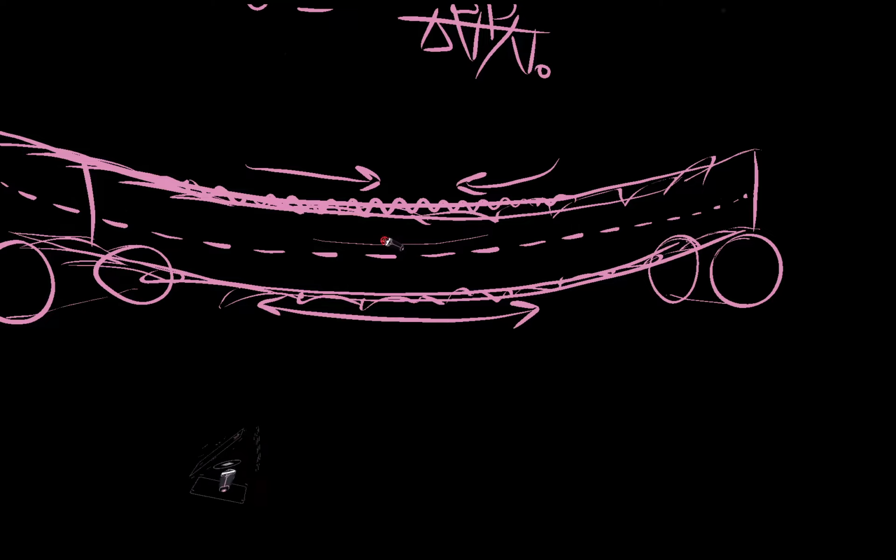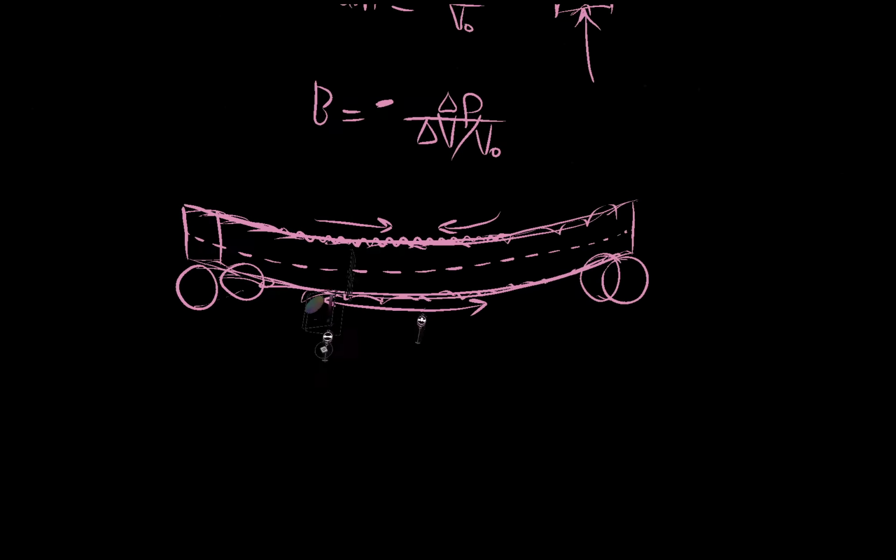And so, consequently, you don't need any reinforcement in the center because it's not experiencing any stress at all at that exact center line, right? But at the bottom, it's experiencing a lot. At the top, it's experiencing a lot. So we can even cut out the center part, or a lot of the center part, and just shave all this part out because it doesn't need any reinforcement there.